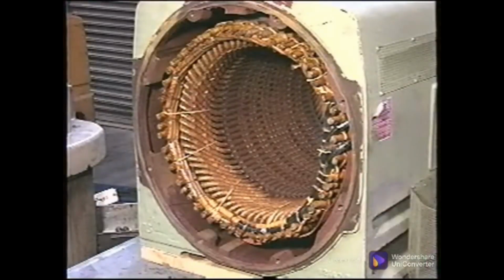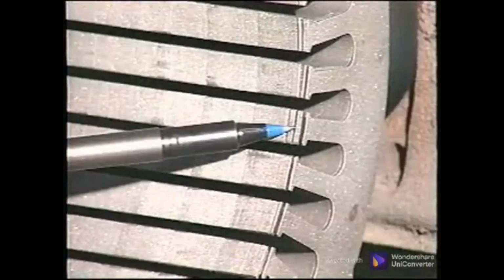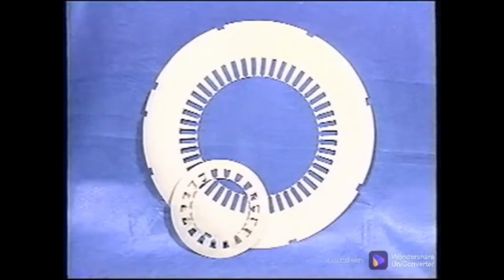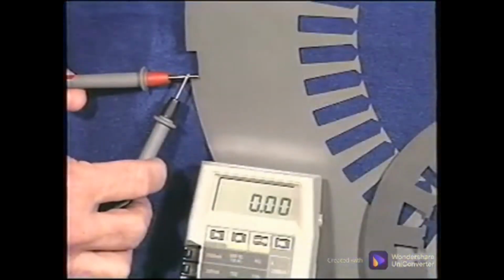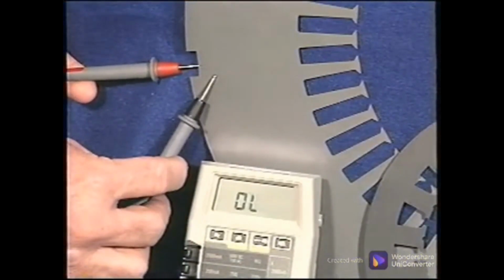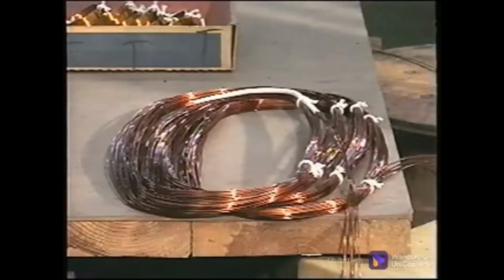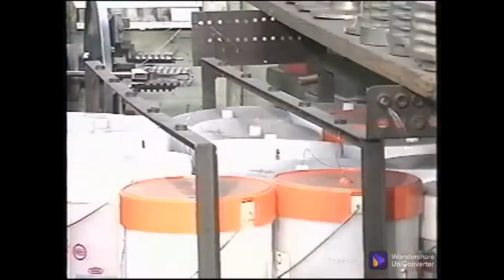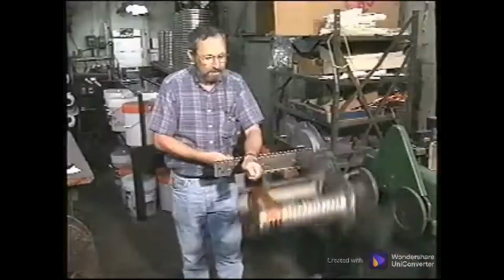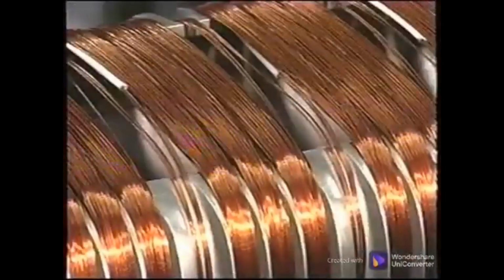The other part of the motor is the stator. It is assembled in the housing. Like the rotor, it has a core of electrically insulated soft iron laminations to reduce eddy current flowing through this core, which then reduces the amount of heat generated. The slots in the core are for coils. The coils are windings made up of individual insulated wires that are wound to the size to fit the core and with the proper number of windings or turns for the prescribed horsepower.